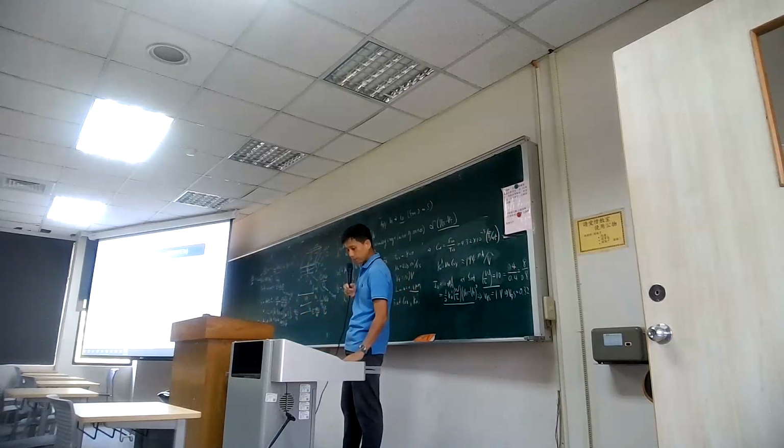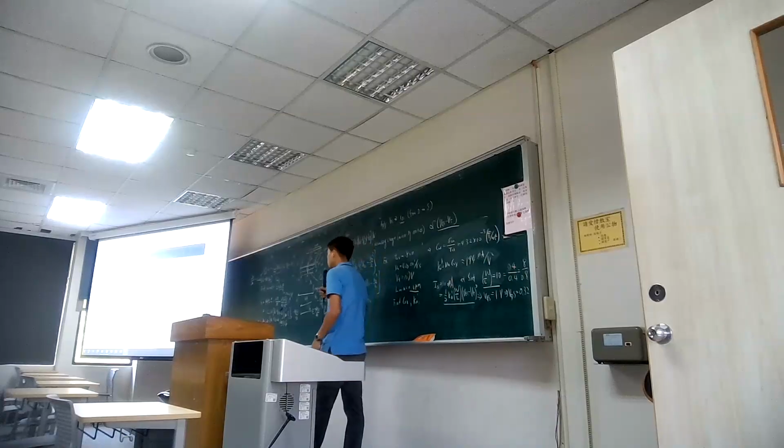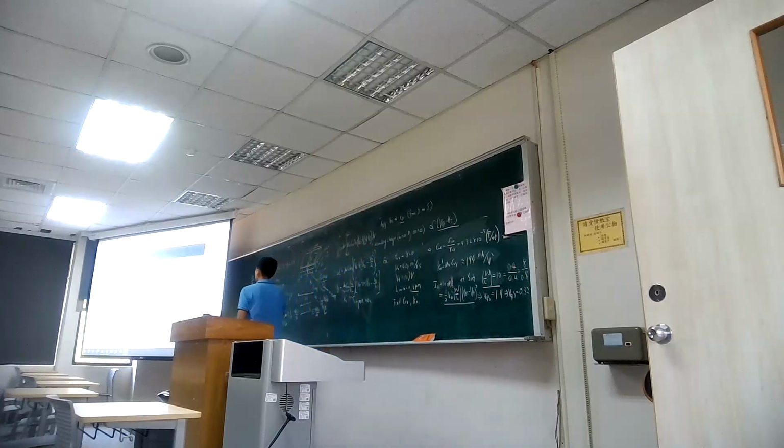Maybe I think this one can go back to the slide. One function we can play with. Okay, this one. So you consider saturated current. What is the parameter we take? W over L is limited, right? Because if you increase the current, of course you can increase the W. But what happens here? You increase W, you increase the width of this device. That means you make it bigger.